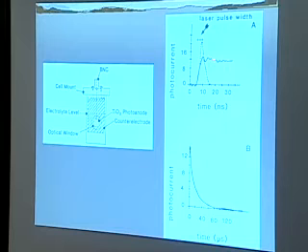I'll point out, when you're looking at the fast time scale here, even though we've done a lot to minimize noise, there's what, if we were doing NMR spectroscopy, we would call ringing going on there. That is, we have a bit of an impedance mismatch between our oscilloscope that we're putting this out to and our wires and our cell here. And so we have some signal bouncing back and forth, and all this ringing here is due to that. So the real signal is on this longer time scale here. So that's the experiment.